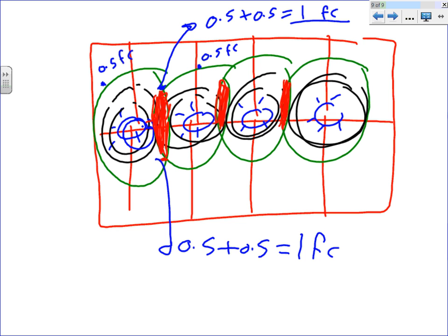The worst thing that could happen to you is you have to have the cutoff though. This 0.5 foot-candle is the cutoff. I don't want any point to be less than 0.5. In a parking lot, sometimes they use 0.25. I want every point to be at least 0.5 foot-candle. It could be higher than 0.5, but I don't want it to be smaller than 0.5 foot-candle because it's dark. So you use that as the cutoff, and then you overlap these two curves of the cutoff.